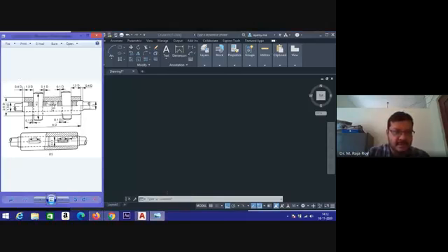If you observe this drawing, the shaft diameter is D. After some distance, it is extended to 1.3D, and from 1.3D onwards the sleeve portion starts. So I'll start drawing this half of the portion, and the other half I can get by using the mirror command. This particular diameter is 1.3D. Just take D as 30 and do the calculation: 1.3 into 30 means 39.